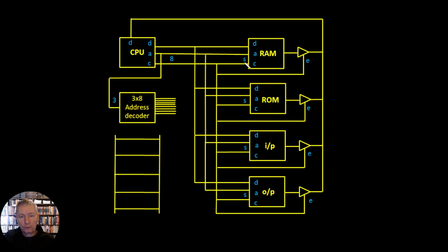Now the control bus will determine whether we're going to write data into the RAM using the set, or whether we're going to read data off of the RAM using the enable. And we've seen that we put this little buffer here, a control buffer, to control the output of data from the device onto the bus. Now equally this little device might as well just be inside the RAM, but we have designed it and we can see it sitting outside the RAM. So I've taken a connection here from the control line just along and round, which controls the data flow out of the RAM onto the bus.